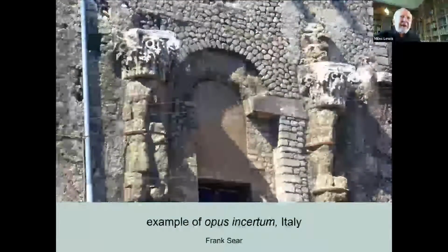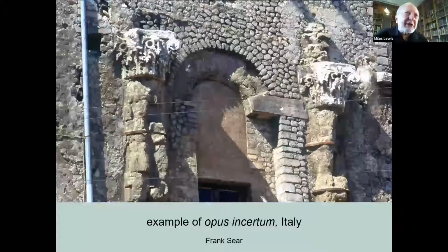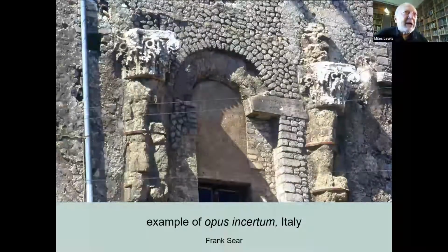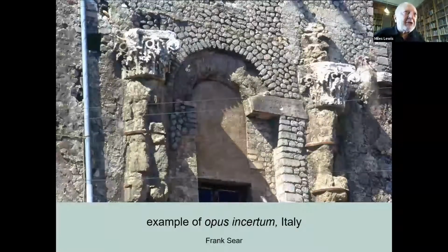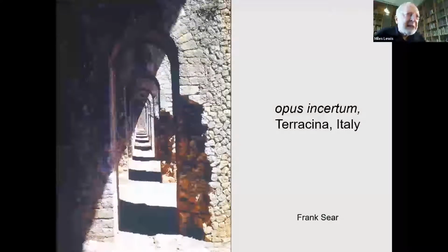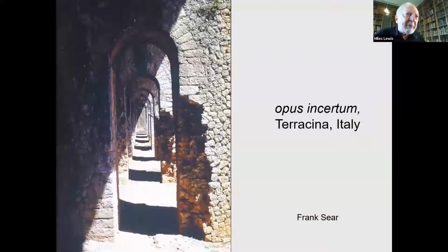And here's now the first phase of Roman sophisticated concrete. On the outside, it looks like a rubble wall. People have stacked up, like dry stone perhaps, irregular stones to create the face of the wall. But that's just the face of the concrete. They've done just what I described to you before. There's another example, see it's broken away. You can see inside that, it's rubble, it's rubbish. It's only the face that's got that nice set drywall effect. So they've built the facing up inside the timber formwork and then packed the rubble and cement in between it.